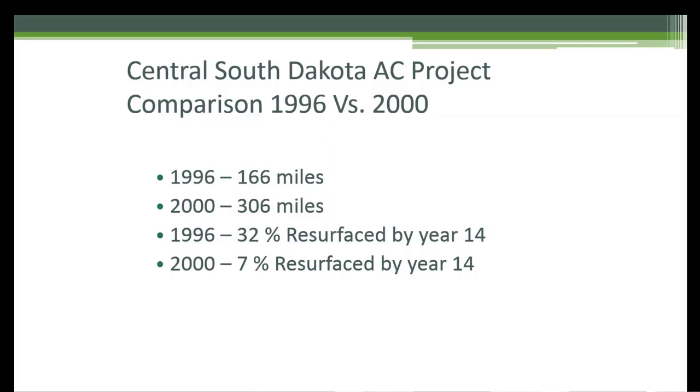So what this data represents, this was done in 2013, 2014, so 14 years old, was all the pavements prior to 2000 in the central region. You could look at the data on how it performed. Every year, what was the cracking index? How much was it rutting? How much was it raveling? What was its basic condition, pavement condition index, PCI? So you had data representing multiple miles, multiple projects, different years.